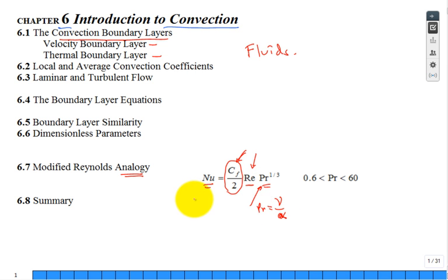And then the Nusselt number, a brand new property, is where we get our convection coefficient. Nusselt number is h times some length scale. So the Nusselt number could be based on diameter, then the length scale would be d, just like the Reynolds number. What is my length scale for the Reynolds number? Here they didn't put a subscript on it. They didn't put x, or d, or l. But you need to know what the length scale is in the Reynolds number, just like for the Nusselt number. Here I'll put d for a length scale, h d over k.